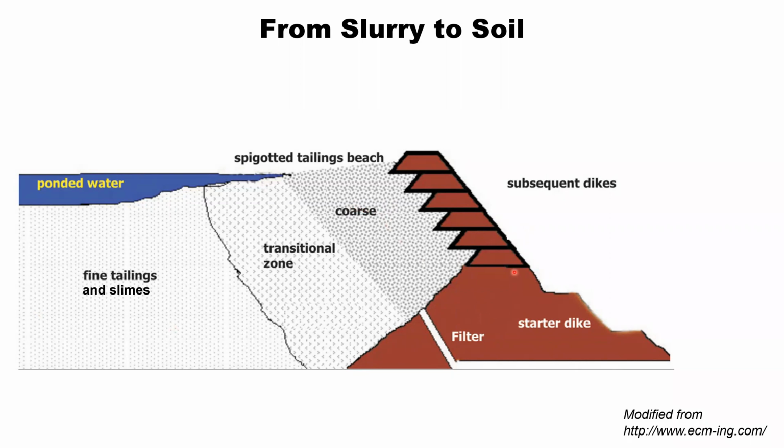Here you have your starter dikes and your raises at the deposition points, typically going from one of these exterior or perimeter dikes being deposited inward. The coarsest materials, so your medium to fine sands, are going to be deposited closest to the discharge points.